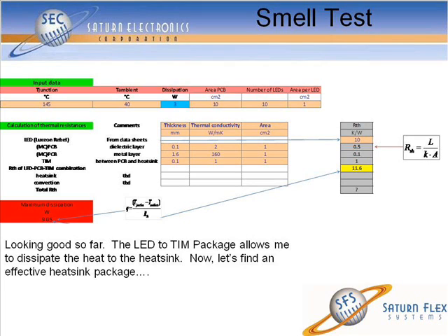The math behind it's pretty intricate, but what we've done is said, well, you've got 11.6 Kelvin per watt of resistance, and the maximum dissipation that you're going to have is 9 watts. So 9 is greater than 3. You're looking good so far. The package is working. You don't need to look at a different type of LED for your product.